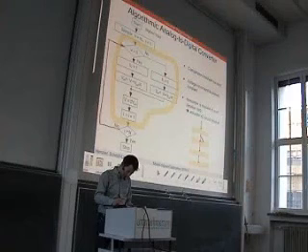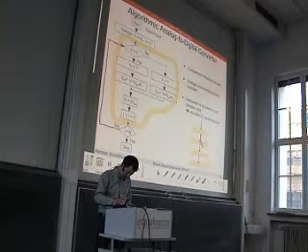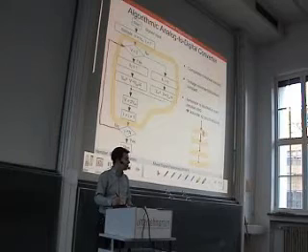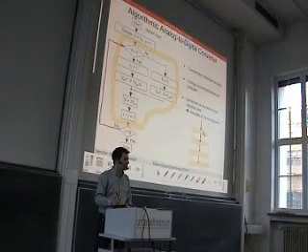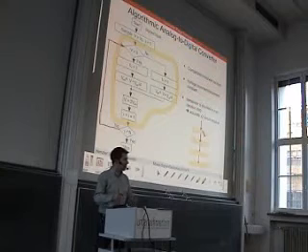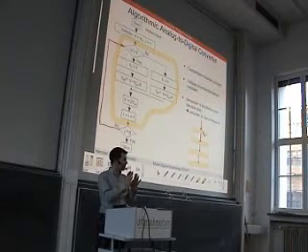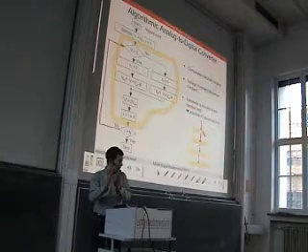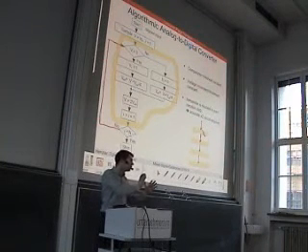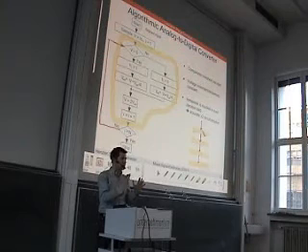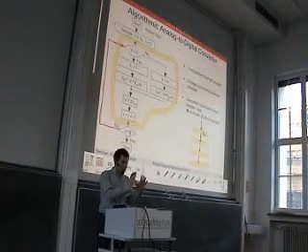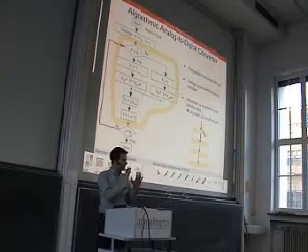So I put this result to the next stage, and I can sample a new input for a new processing. This is the pipelining concept. I do one iteration cycle in one stage, then I pass data to the next stage, and therefore I pull in new data into my actual stage. So data ripples through these n stages step by step.